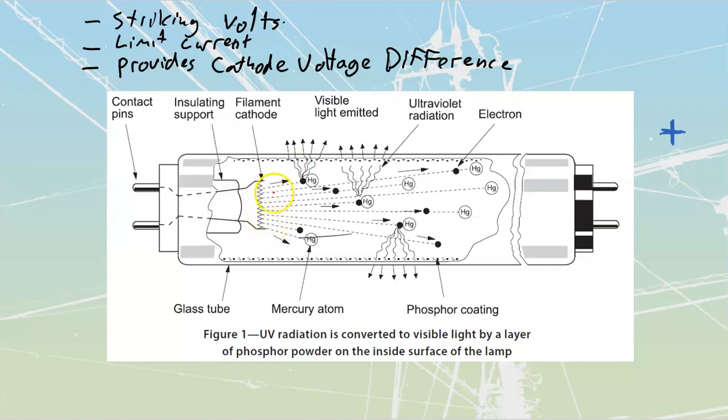Tungsten has a high amount of inrush current anytime we have it cold, and then it is going to settle in. But that causes a large amount of thermal expansion because it goes from being very cold to very hot inside of this thing, which means that there's massive amounts of movement. That's where your filament breaks.